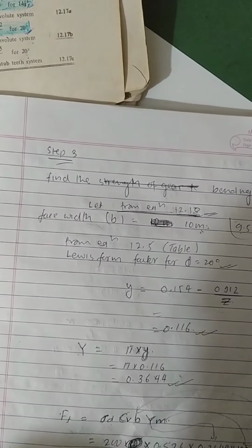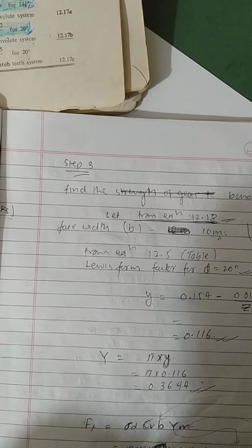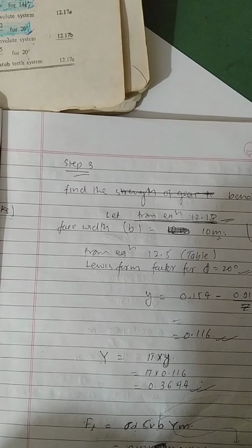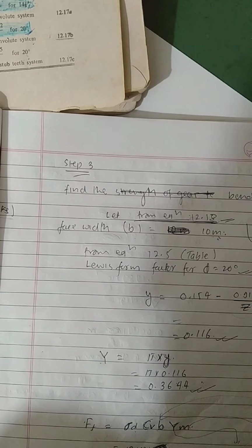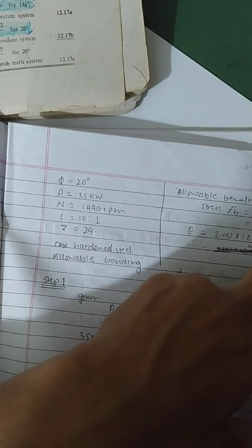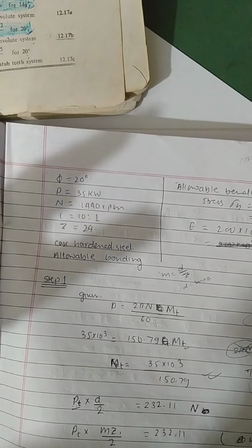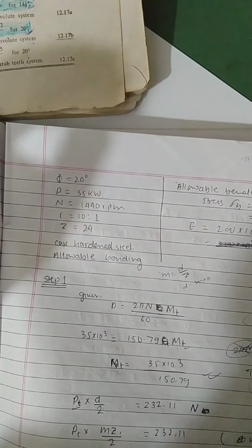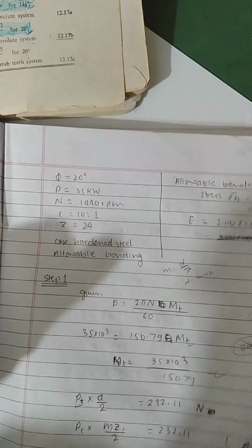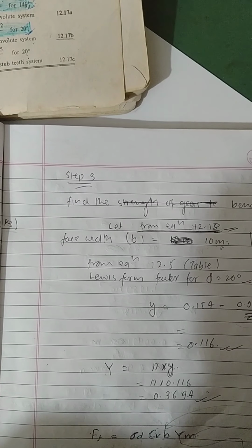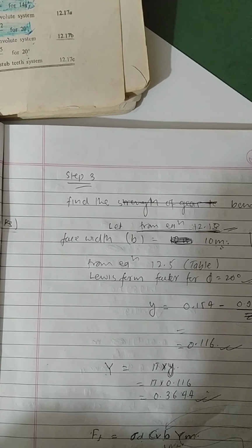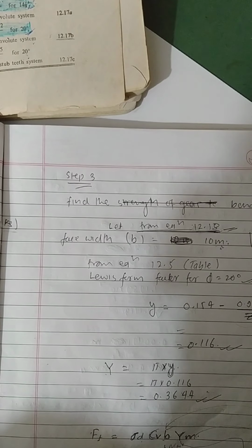If you have any problem with how we got this 10 to the power 6: the unit of this 200 Newton per mm square is what? I had converted it into meter square. It's in SI unit, guys. Here it is given as 200 Newton per mm square, but if you are doing any calculation, you have to take all the things in the same unit. So I am taking the same unit, into 10 to the power 6 Newton per meter square. After that we will solve this one and we get these things.